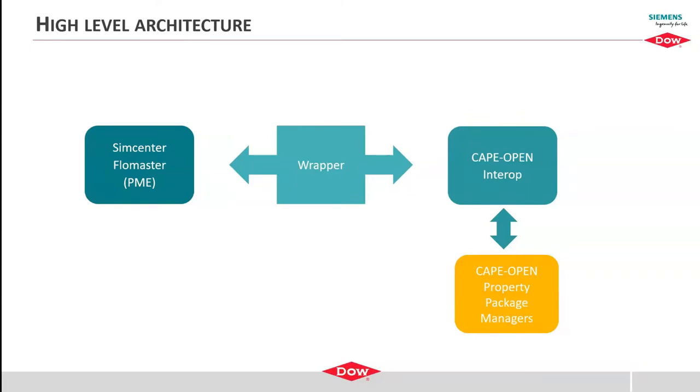This is where Flowmaster requests different fluid properties, like density or viscosity, at different pressures and temperatures for a particular fluid. And once we got all the required data, this is our fluid creation layer, where we create curves and surfaces from the data retrieved from property packages. These curves and surfaces will be assigned to a newly created fluid, which I'll demo in a minute.